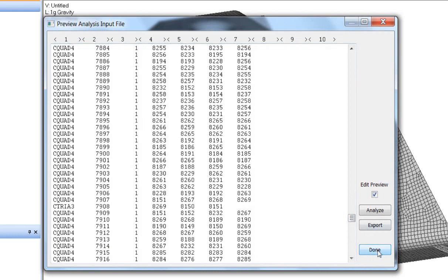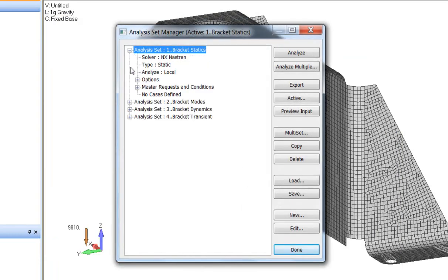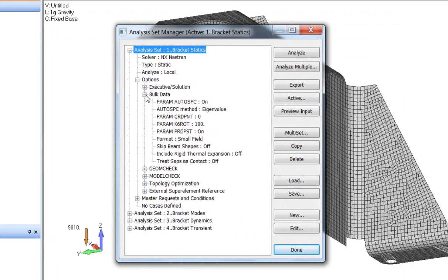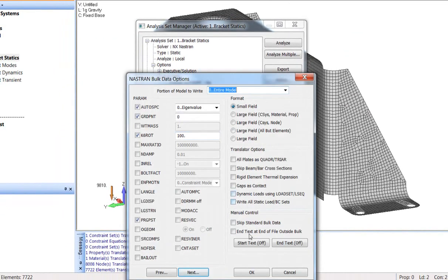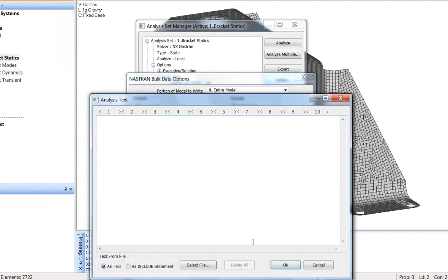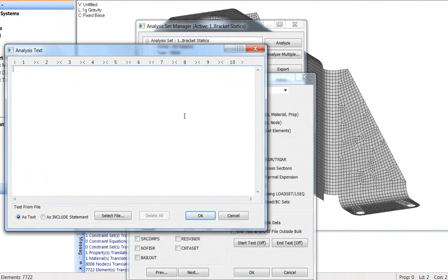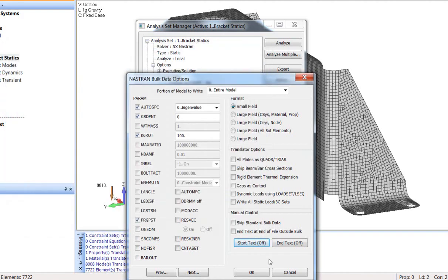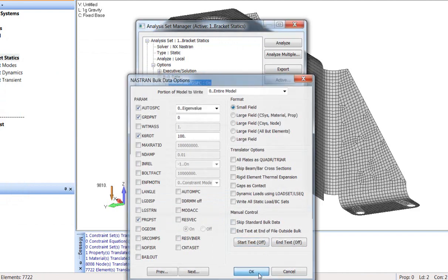So this would be a one-time edit if you did it. But there's also the ability to put edits into your file that happen every time. So I could go into the bulk data section of a Nastran run, and we can actually include files. I can include an external file with some additional Nastran input cards that could add some features or things way outside of Femap's support range. It also allows the analyst to even organize your models. If there's parts of your model that you use over and over, you might have a component as an include file, so you could have it there and not have to have it in the visualization side. So these allow you to get the model out in the format you want.